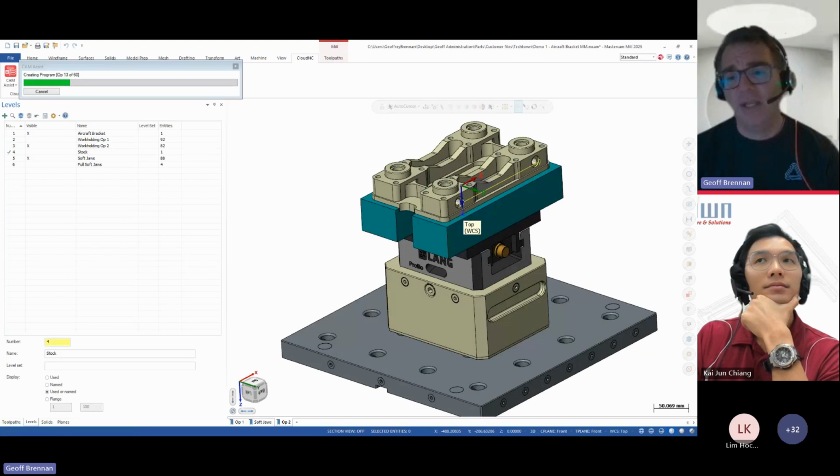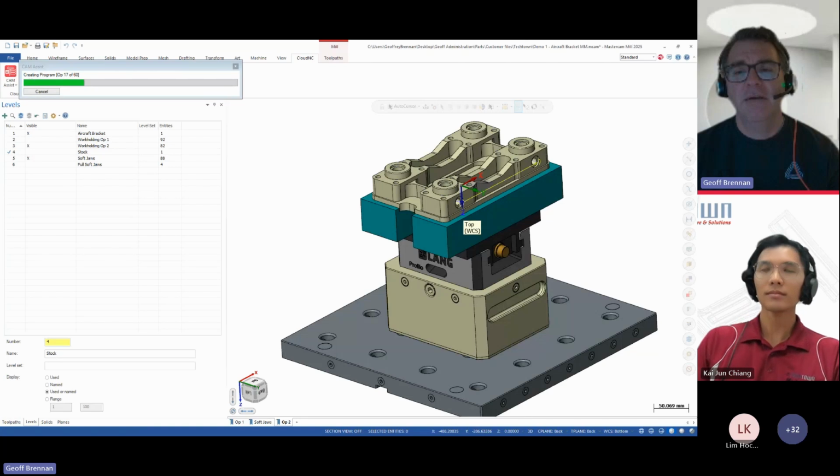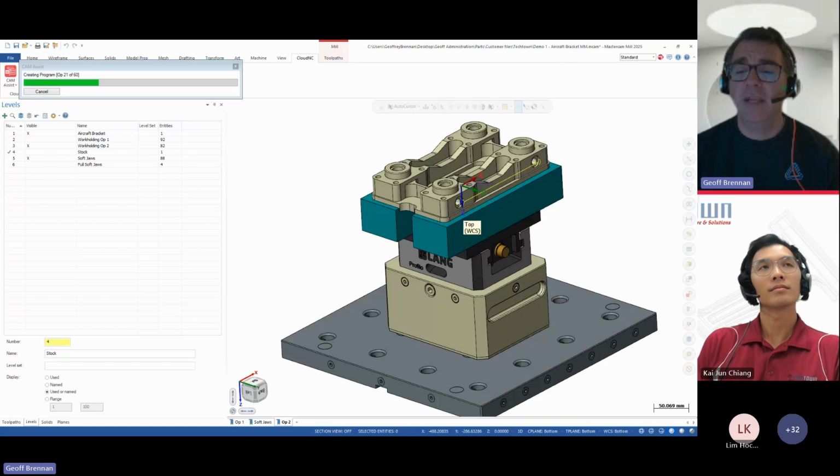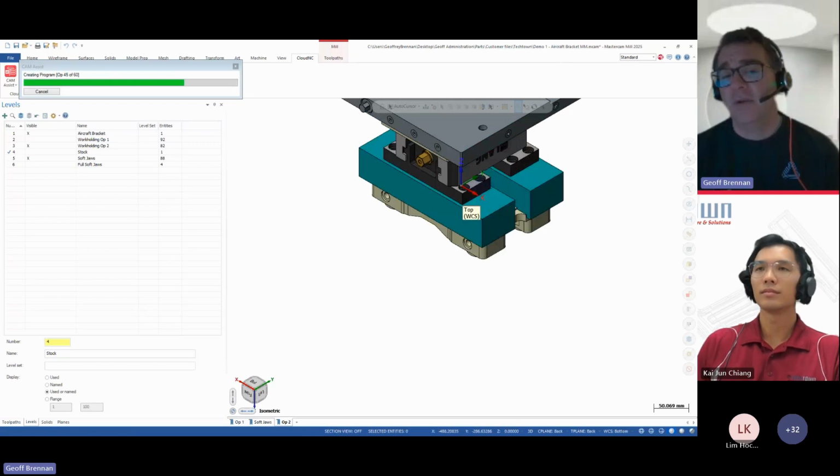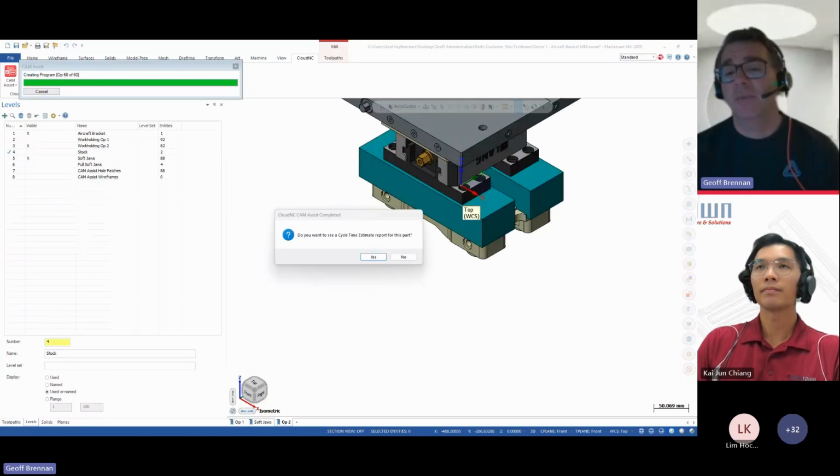In terms of precision machining, I hinted a bit that the basic tapping is not really addressing the core problem so much as fulfilling a short-term need until we get to more precision in terms of GD&T tolerancing, using things like the STEP AP242 format to take in GD&T tolerancing right from the 3D CAD model, and then applying the appropriate probing and conditional logic in terms of the toolpath generation for that type of output.